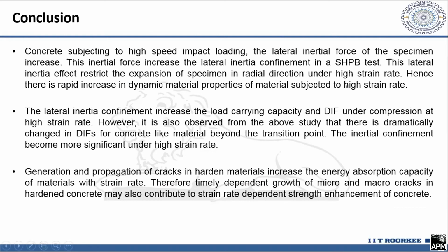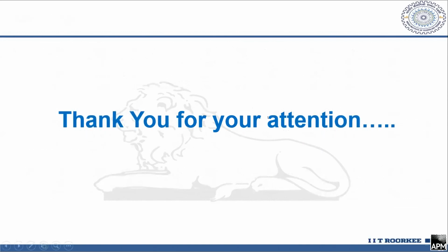Besides this, there are many other possible effects, and one may be the end friction effect that tries to restrain the expansion of the specimen at the interface of the material and the bar. Another important conclusion that may be possible is that the generation and propagation of cracks in the hardened material increase the energy absorption capacity of the material under high strain rate loading. Therefore, time-dependent growth of micro and macro cracks in hardened concrete may also contribute to the strain rate dependent strength enhancement of the concrete. Thank you for your attention. If you have any query,